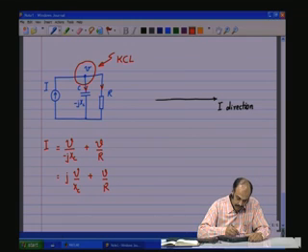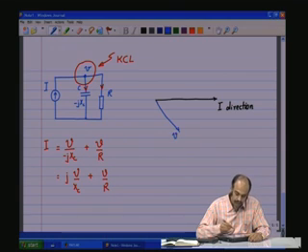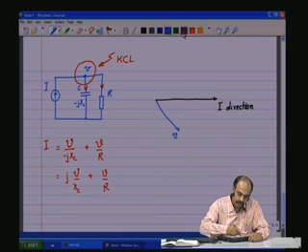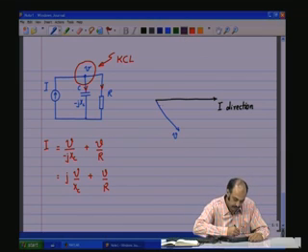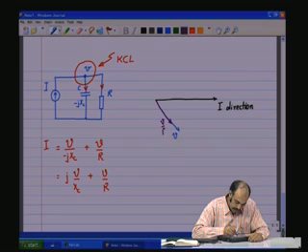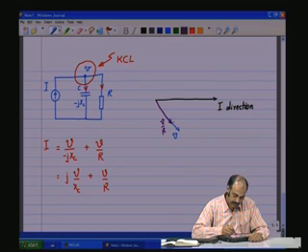Let me put it like this. We have a voltage V direction. So, in that V direction, there is one vector which is along it, and I will call that one V by R. Now, V by R plus j V by X C. Now, V by X C is multiplied by j, which is along this, it is plus 90 degrees.